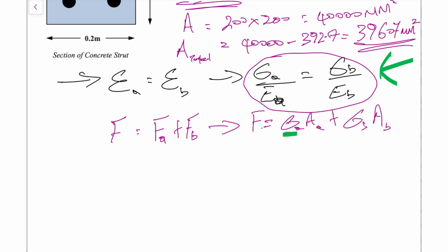And this is the final step to get our formula. So force would then be equal to, so we're now substituting our stress A with stress B times modulus of elasticity A, and all divided by modulus of elasticity B, multiplied by area A.